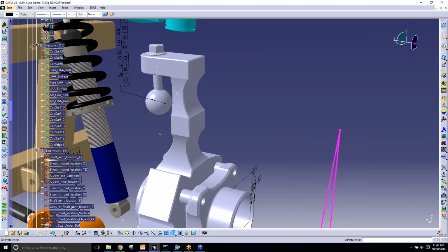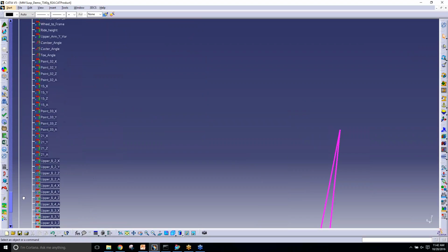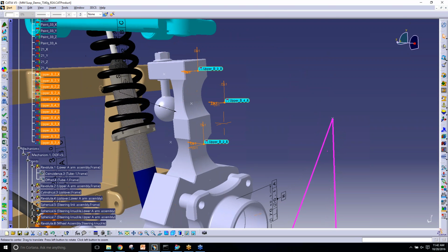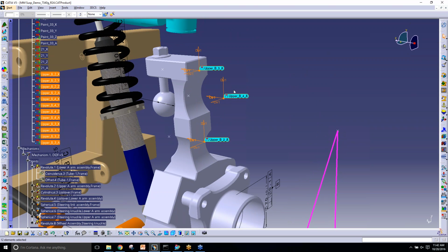So now once I go down here, here's all my new measurements based on an XYZ. You can see the directions here: the XYZ directions and an associated vector direction. One of the common uses of measure generator is to put measurements in the XYZ direction on all your piece part points, and you run your analysis up front to actually see, do each of your features have the right tolerances that go in the right direction.